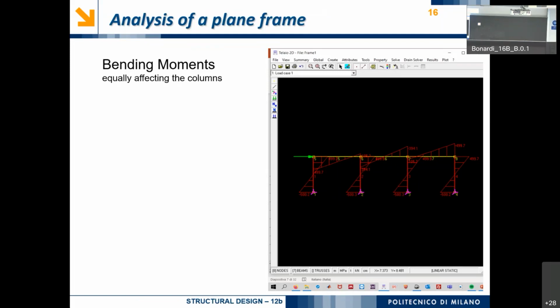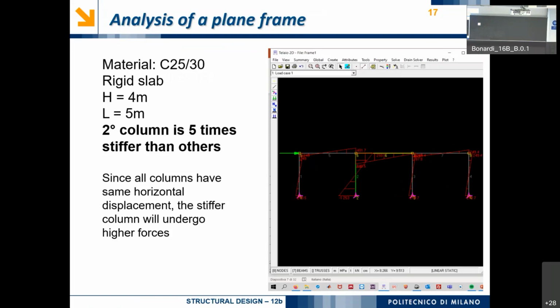When we alter this hypothesis, it means that some element is working more than the others. When we are dealing with torsion in a bolted connection, some bolts work more than others, but that's only because of the deformation of the structure. When we see a bolted connection with a shear force, the shear force will be distributed along all the elements homogeneously.